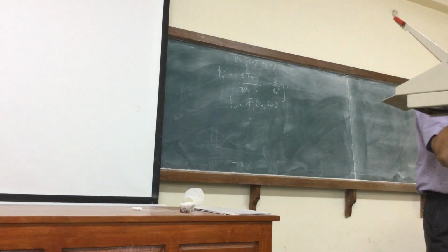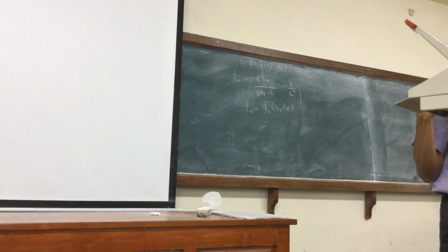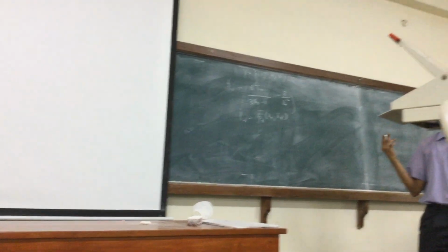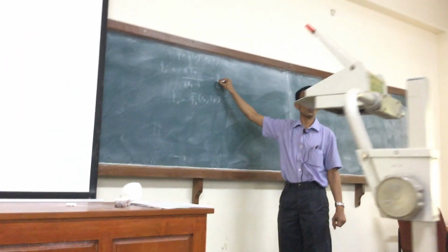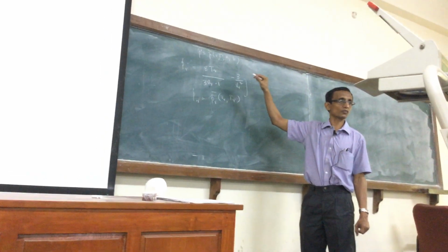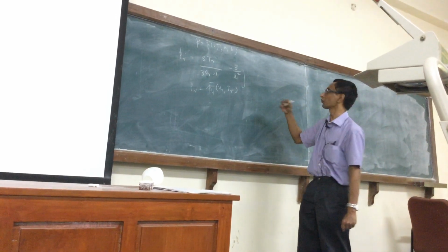Whatever may be the values of A and B for a particular van der Waals fluid, and I take another van der Waals fluid, it will have a different A. However, the equation in terms of the reduced pressure, temperature and volume will be the same for both van der Waals fluids. Let's now consider two states of two different fluids.